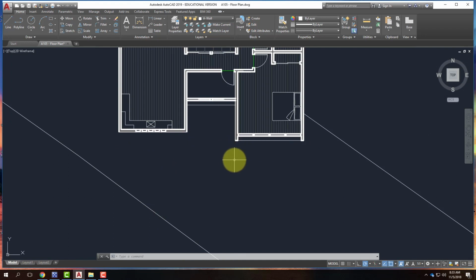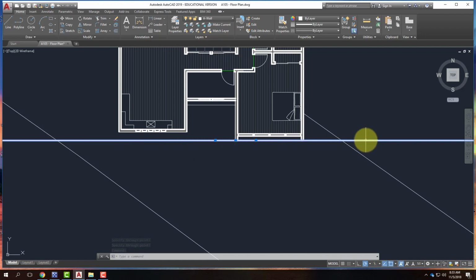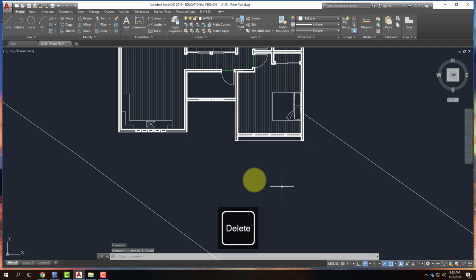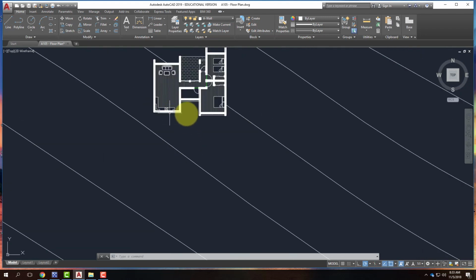And so when we draw a building elevation, essentially what we're drawing is we're pretending as if there was a flat sheet of paper that ran right along the outermost, or in this case, the southernmost edge of our building. So if I had a really long line that went like that on both sides, when I draw the building elevation, I'm drawing it straight on that surface as I look through it. And so when we start to set this up, I can use the floor plan as a guide for how I'm drawing the building's elevation. And I'm going to draw this building's elevation directly below it right here.